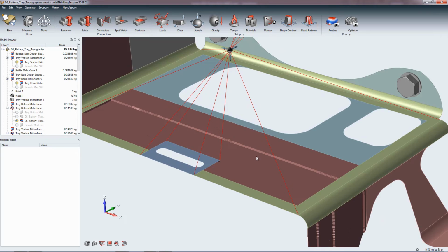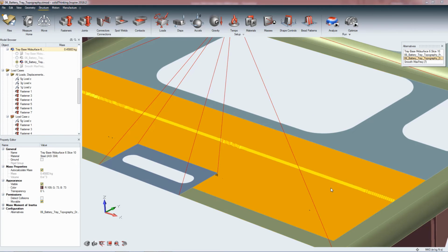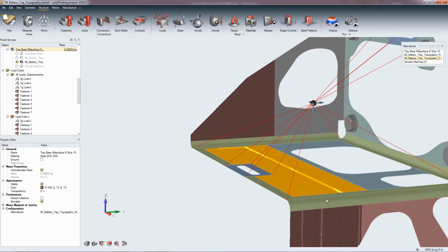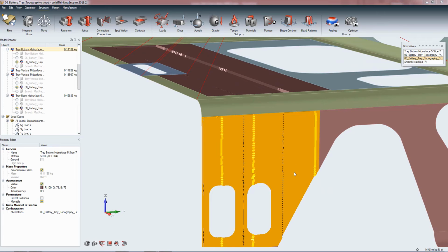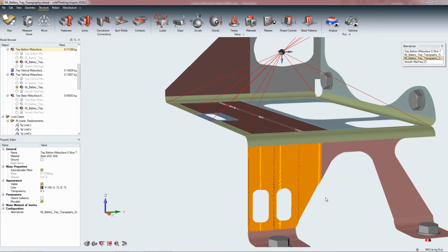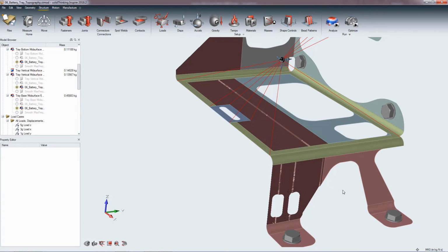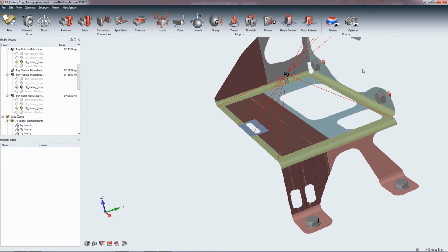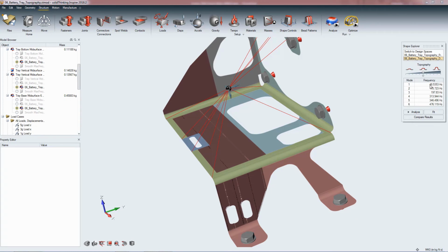This is with the bead pattern created. You can see some pattern, some beads here and here. We can check the performance of it. The first frequency is now 48 Hz. I have more room to reduce its thickness.